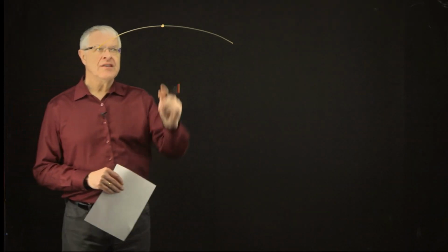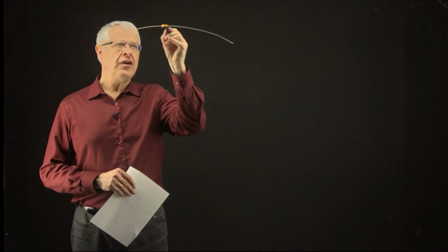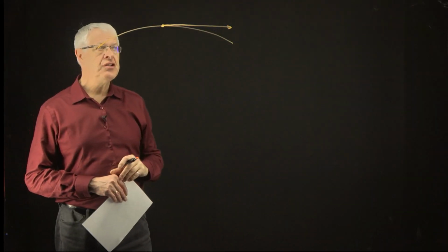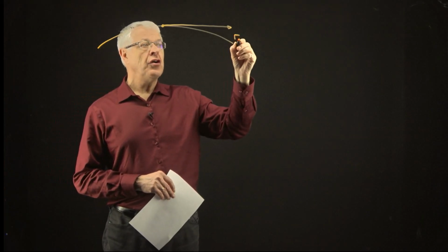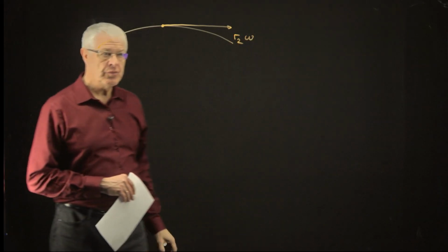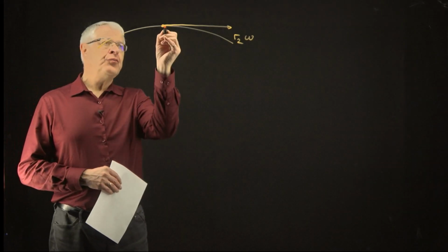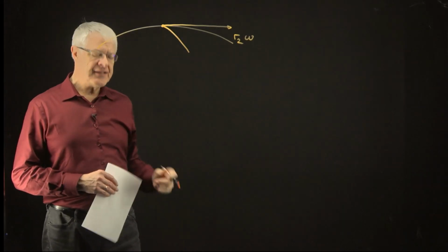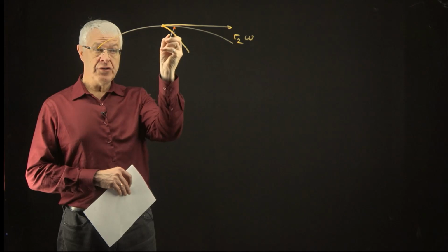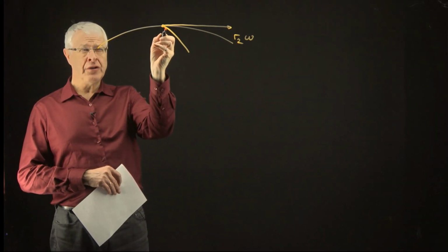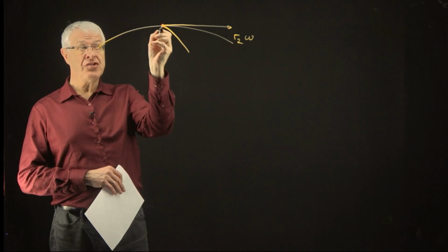So remember that the impeller itself is traveling in this direction because it's rotating in the clockwise direction here at a speed of R2 omega. So remember, we're working on the outer edge here. The impeller at this point looks like that. And this angle right here is 30 degrees. So realize the water leaves the impeller relative to the blade, tangent to that.